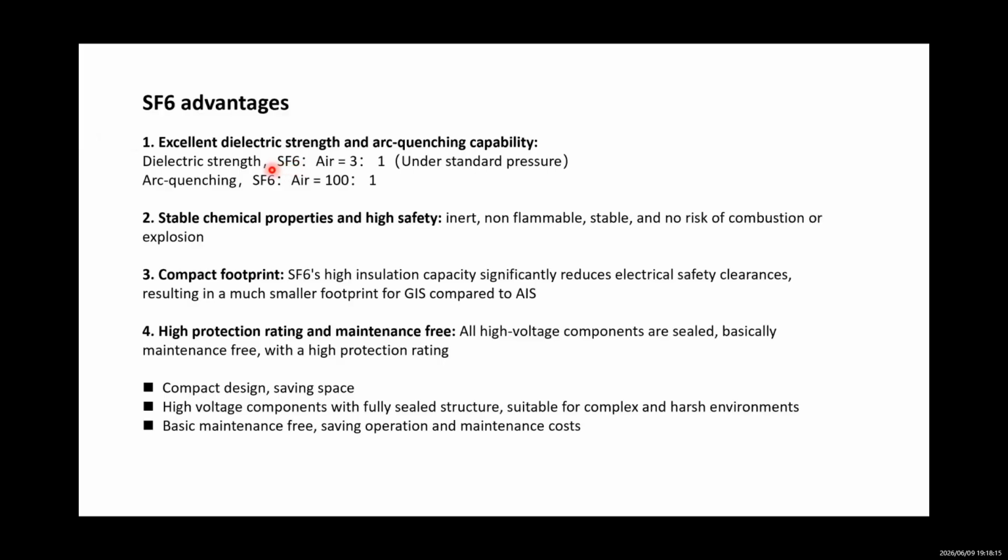Here you can see SF6's dielectric strength is 3 times that of air, and for arc quenching capabilities, SF6 is 100 times that of air. So SF6 has excellent insulation and arc extinguishing capabilities.